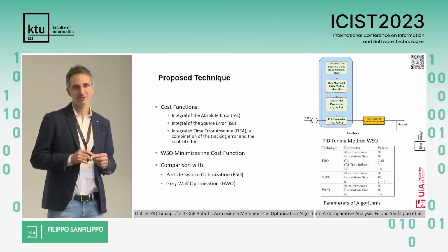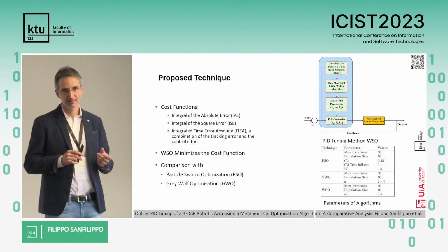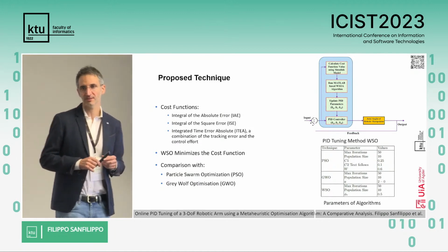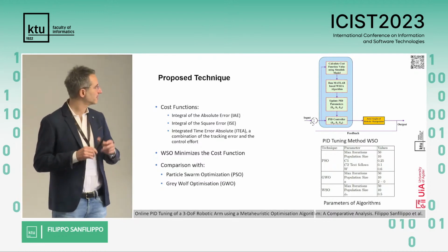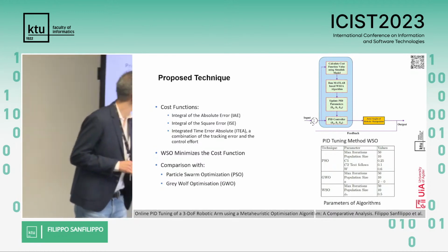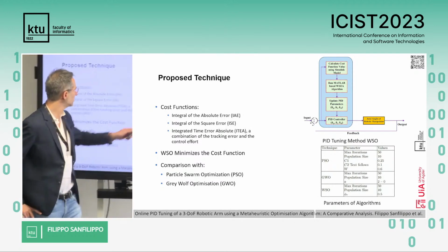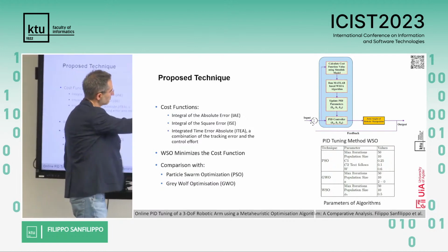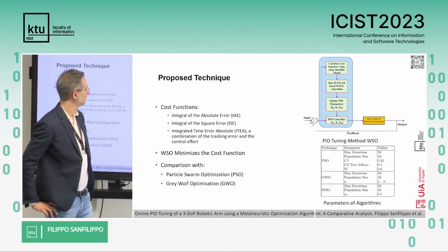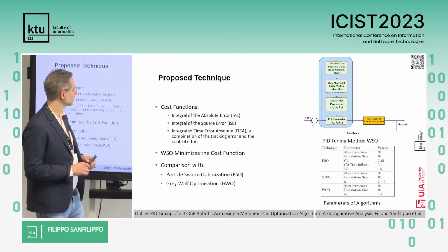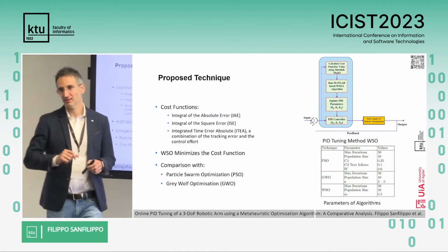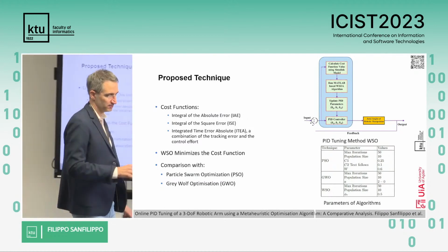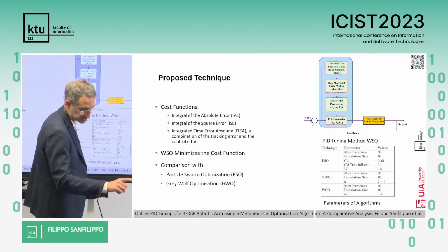The proportional gain, the derivative term, and the integral term. So Kp, Ki, and Kd. Then we use these parameters and we run one control iteration with our robotic arm. That means that we move the robot to the target position and we assess the error. Are we getting to the target position or are we still far?